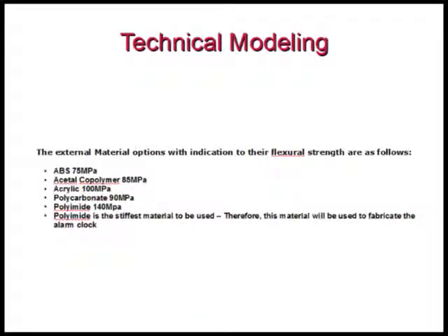5 main types of manufacturing materials were sampled for flexural strength, and polyamide ranked the highest. This qualified polyamide to be applied to all prototypes of the concept design. After calculating the volumes of the shell of all prototypes, we then calculated the estimated mass of each concept design so as to select the design which will prove most effective on weight and be selected to supersede in terms of this parameter.